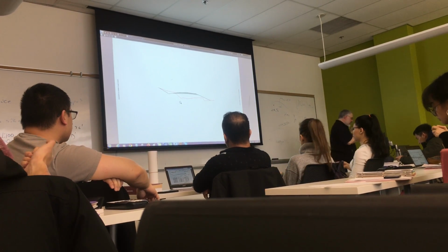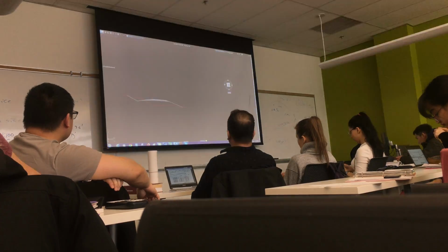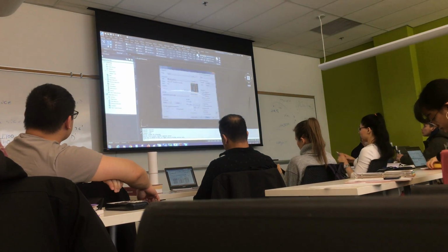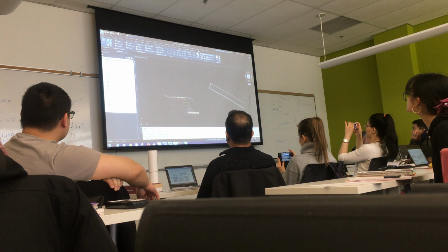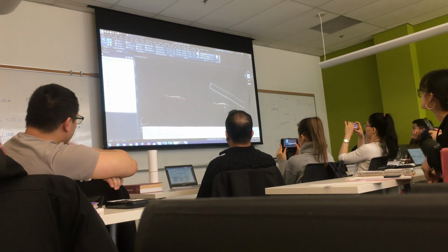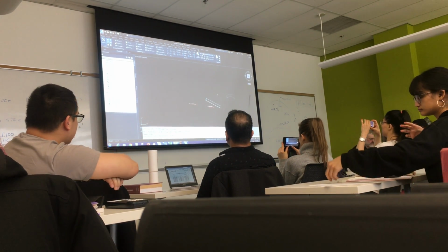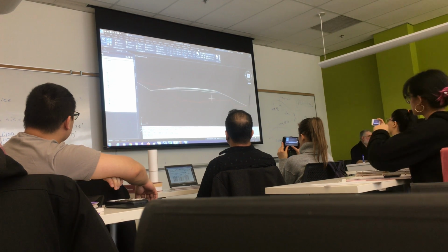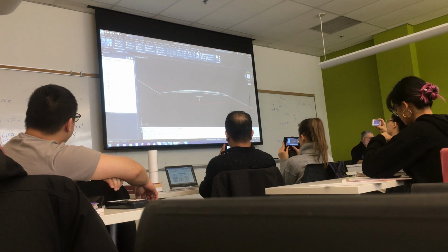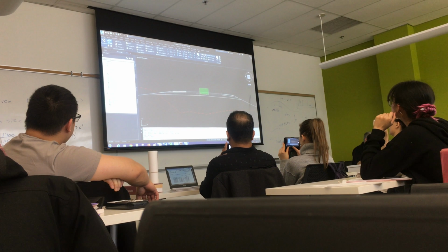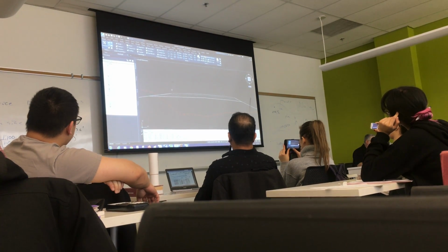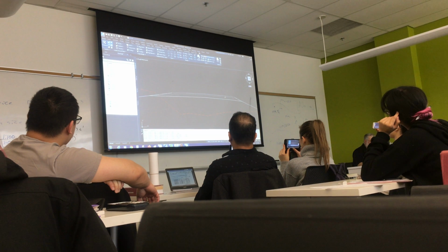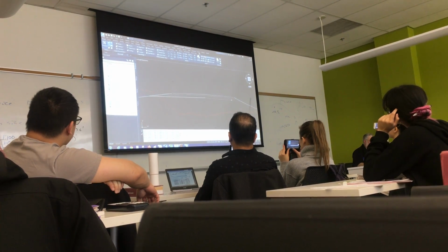When you're performing an earthworks exercise, remember, we don't build the finished ground. We build the subgrade. I'm going to make a copy of this just for discussion off to the side. I'm going to take this and put it over here. Get rid of this. So there's my design. What am I building with the native earth? Well, I'm going to erase these layers. These are the construction layers, the asphalt, right? The granular. None of this has to do with earthworks.